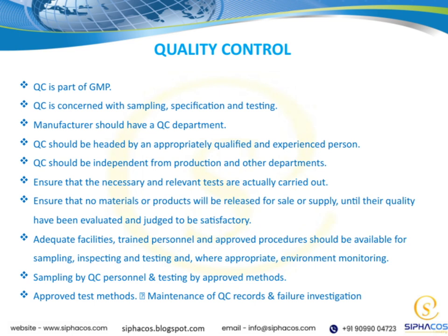No product or material should be released for sale or supply until its quality has been thoroughly evaluated and judged to be satisfactory. This helps us prevent any substandard products from reaching our customers. Furthermore, QC must have adequate facilities, trained personnel, and approved procedures in place for sampling, inspecting, and testing. When applicable, they should also monitor the environment to ensure the testing conditions are appropriate.